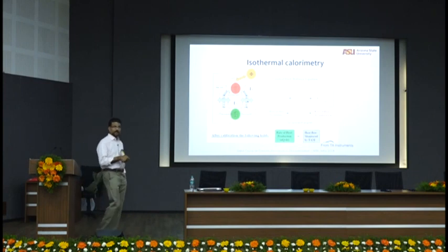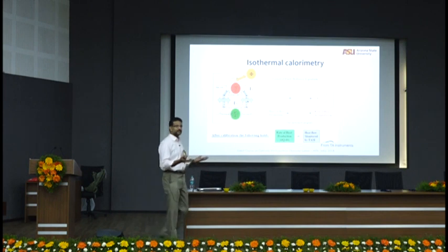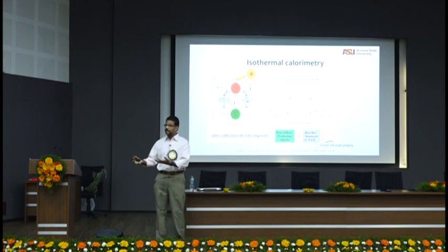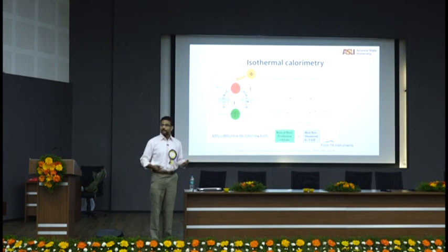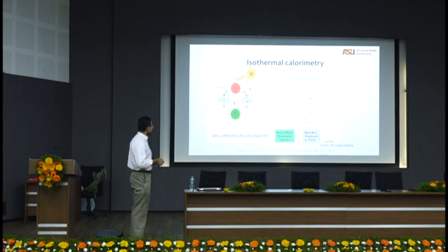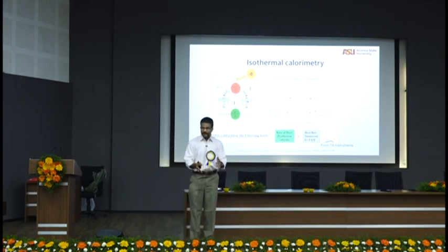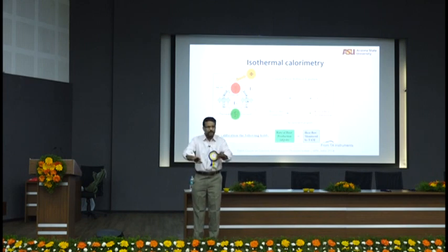Rate of heat production. Think of your cement hydration as an internal combustion engine. Produce heat, use up the heat, throw away the remaining heat, right? It produces heat. Again, instead of mechanical energy, you are producing chemical energy. Heat through a chemical reaction. So rate of change of heat with respect to time is equal to rate of heat exchange plus rate of heat accumulation. So if I have a box of concrete that I'm casting now, the cement that's hydrating is producing heat. Some of the heat is accumulated within, some of the heat is dispersed out, right?